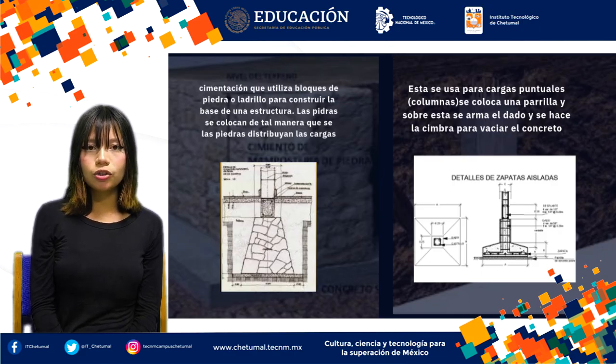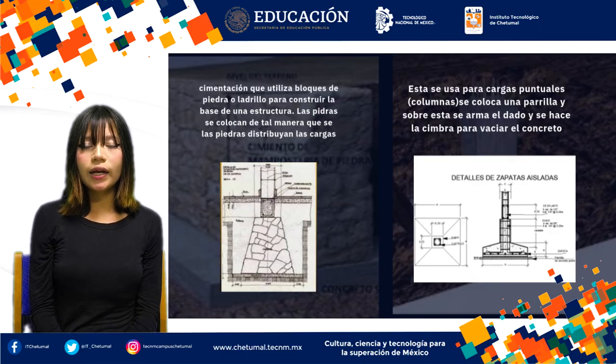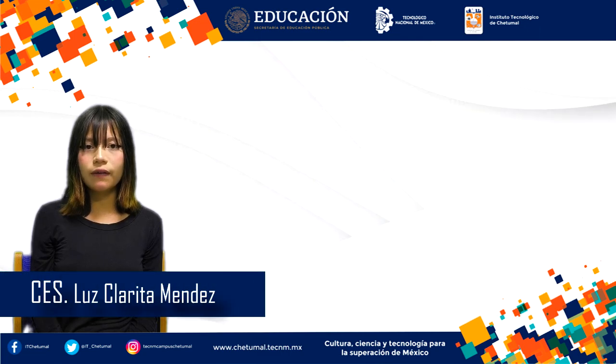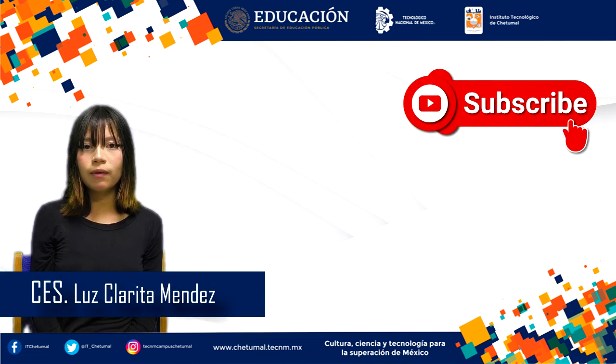Construction. Like footings, pedestals require steel reinforcement inside to ensure their strength. They are placed directly beneath the columns and connected to the existing foundation. Advantages. They are ideal for local reinforcements in columns or areas where loads are concentrated. Although they do not support large areas like footings, they are key for the stability of individual columns.